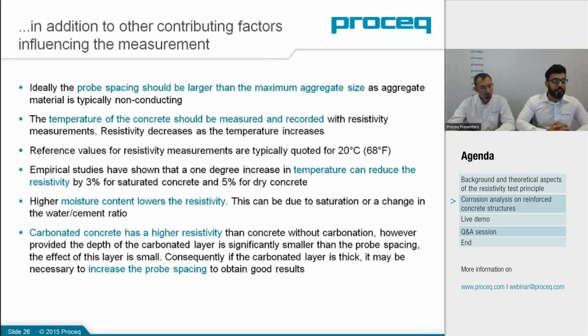On the other side, higher moisture content drastically lowers the resistivity, so you need to take that into account as well. Carbonated concrete has far higher resistivity than concrete without carbonation. So again, it is important to increase the probe spacing to obtain more stable results in such scenarios.